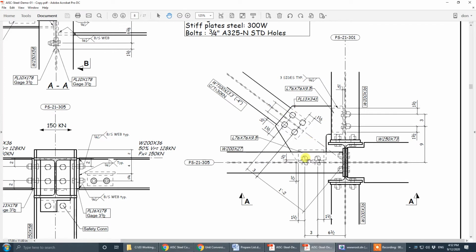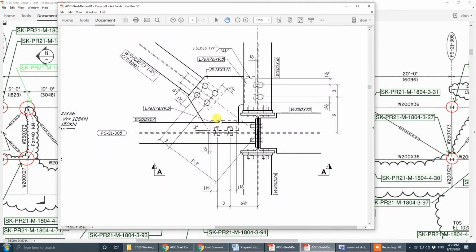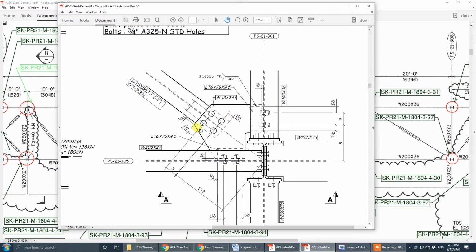Okay, so that's a wraparound gusset plate. The beams are 236 and 227. Okay, the WT 100 by 13.5 should be all right. So the beam is 227, 236. Okay, 236. So you see here 236, 227. Okay, so it's just flipped upside down. On the plan view it's like this, but it's flipped. Okay, don't worry. So we'll do this wraparound gusset plate.